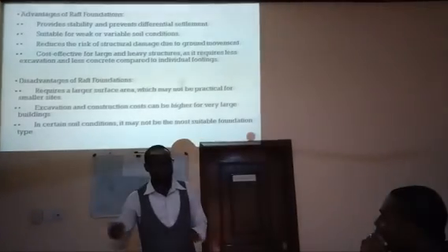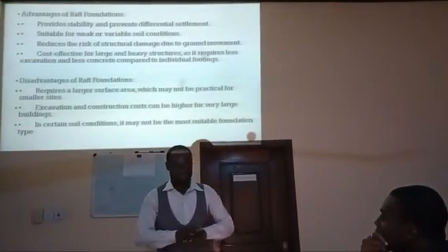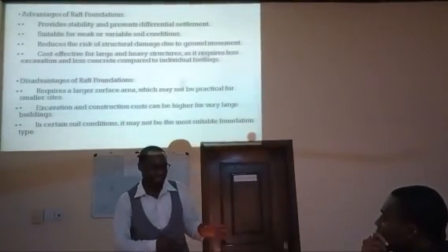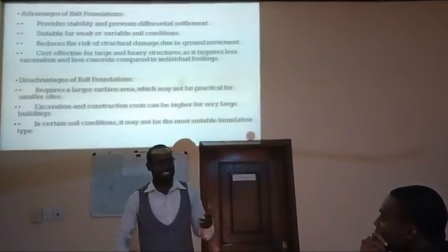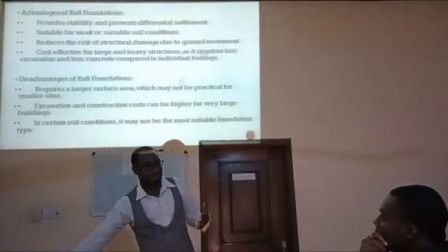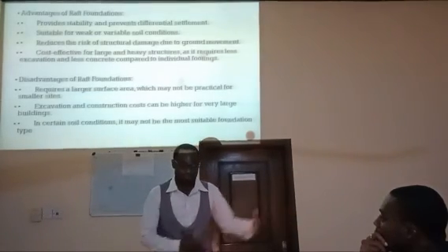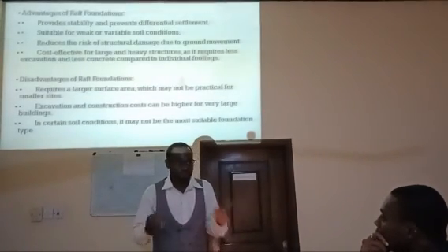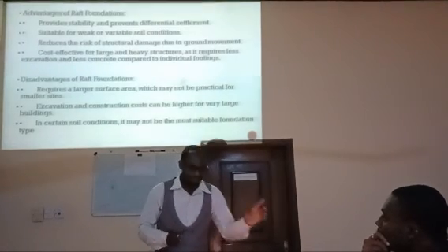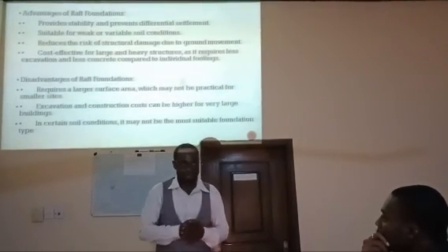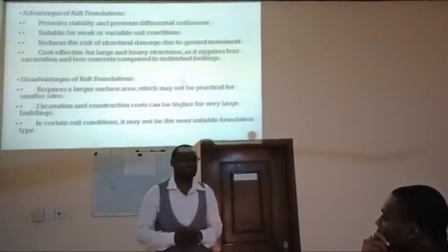Okay, and then the disadvantages. It requires a larger surface area, of course, which may not be practical for smaller sites. Number two, excavation and construction costs can be higher for very large buildings. Number three, in certain soil conditions, it may not be suitable for foundation types.